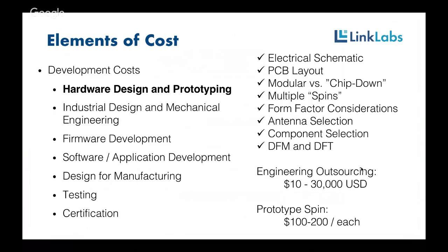In the DFM, design for manufacturing, design for test. One great way to save a lot of money is to make your PCB easy and cheap to assemble and easy and cheap to test. And a lot of hardware engineers don't think about those things from the get-go, but understanding how your design is going to be tested from an in-circuit test or a functional test, what kind of jigs are going to be used, having those requirements set in the beginning is always going to save a lot of time and money.